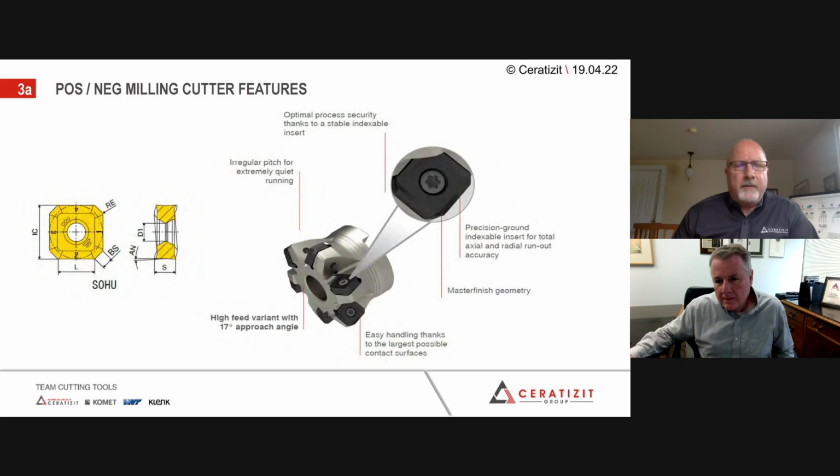Yeah, I think that's an interesting question because historically, some of these original designs were made to sort of conventional dimensions, and operators were very concerned about the fact that the wear scar was impinging on the opposite edge. So they were concerned about the inability to use all the edges of the insert.